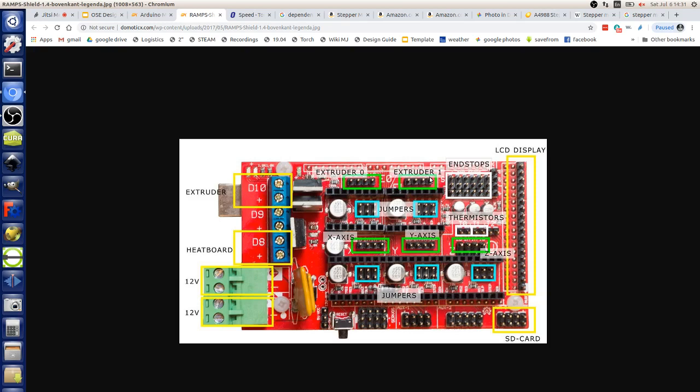I noticed on your printers the end stops are the 1st, 4th, and 5th channel. Why not 1, 3, and 5? That's typical. However, that depends on minimum or maximum locations. We do have one on maximum, which is Y. You see the end stop is on the far side, which is positive Y. That's why it's going to be 1, 4, and 5, because Z is actually minimum, the minimum distance from the bed. So it's 1, 4, and 5 for where we plug in the end stops for the D3D motion system, for the 3D printer.